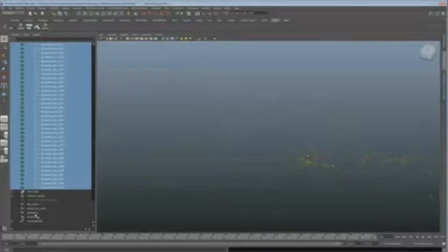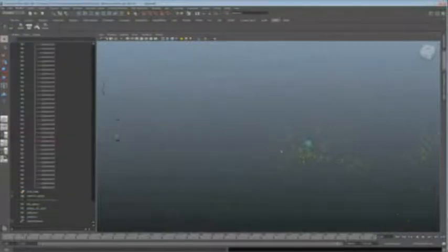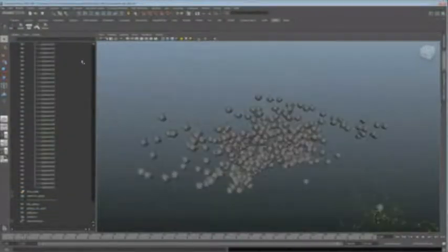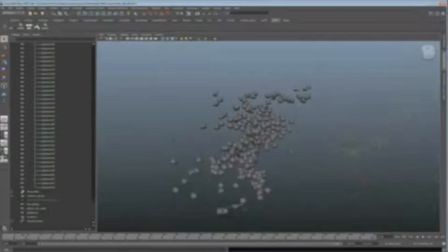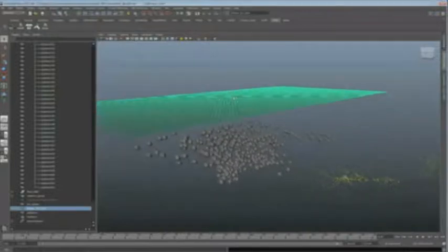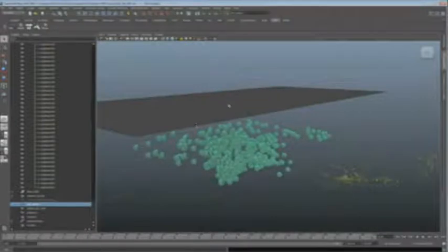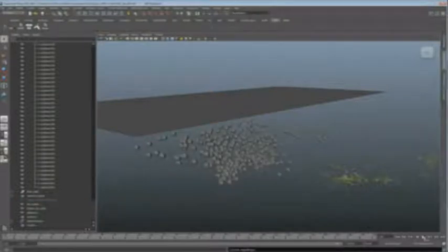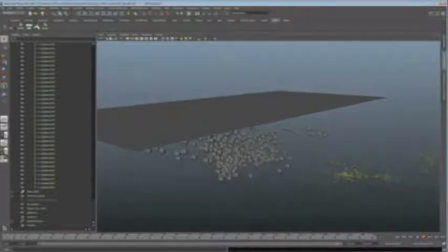So this is now ready to be exported and used in a CG application like Maya to build geometry to send back to us. So with Maya, we'd import the point cloud and camera and actually add a single sphere to the scene and replace all the points, in this example in the cliffs and the trees, with spheres. And that gives us something for a cloth type material to drop onto. We're going to use the N-cloth simulation and actually just freeze a simulation with a cloth dropped over these spheres to really give the impression of a kind of a mountain range and ground plane.